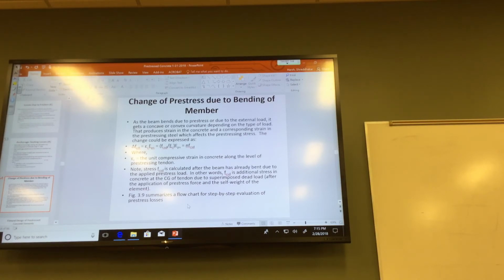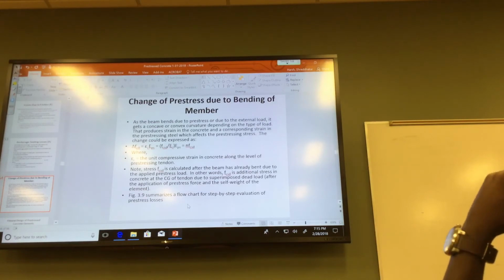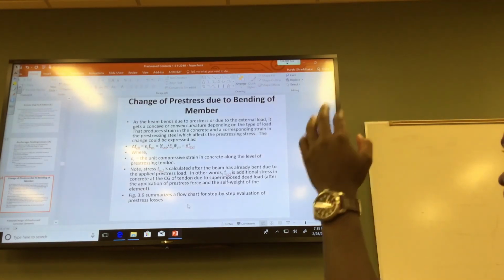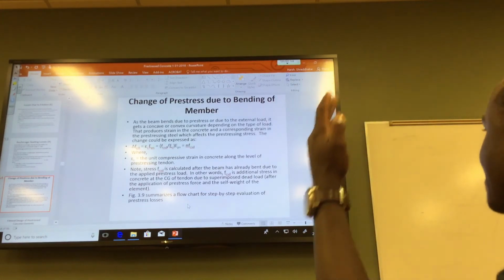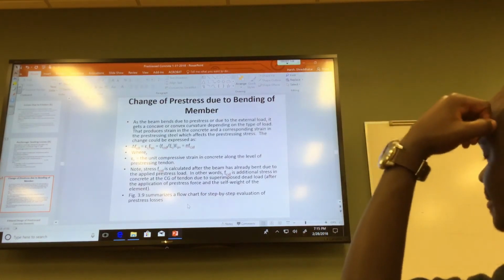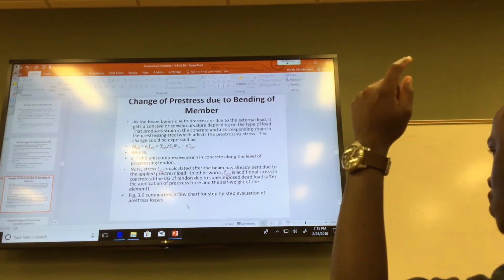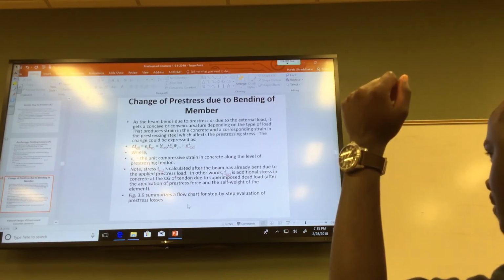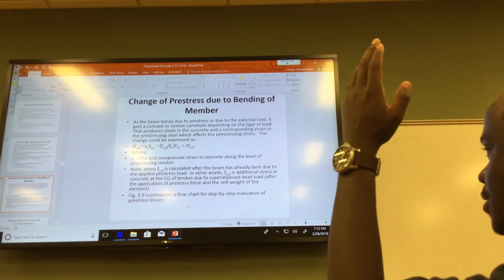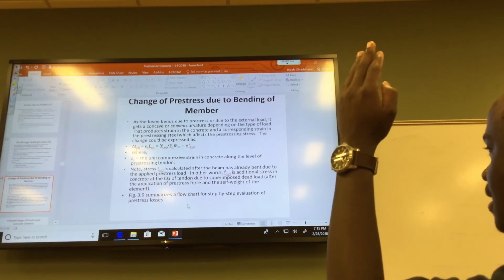We are looking for something that is either permanent or close to permanent, right? We're looking for sustained load, because creep. If I put a load for a few seconds or a couple of minutes or even half an hour, it will affect the creep. The creep will be more. But in the scheme of things, when you are talking 5 years, what is half an hour or even 1 day, right? Nothing. So what we do is we disregard the live load.